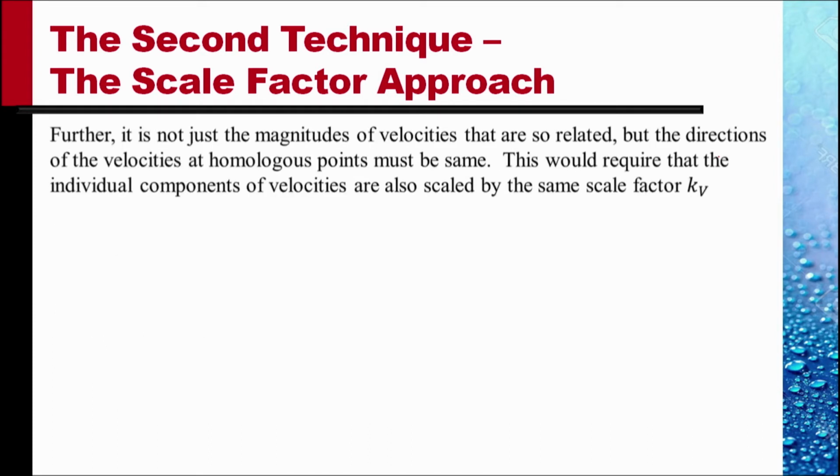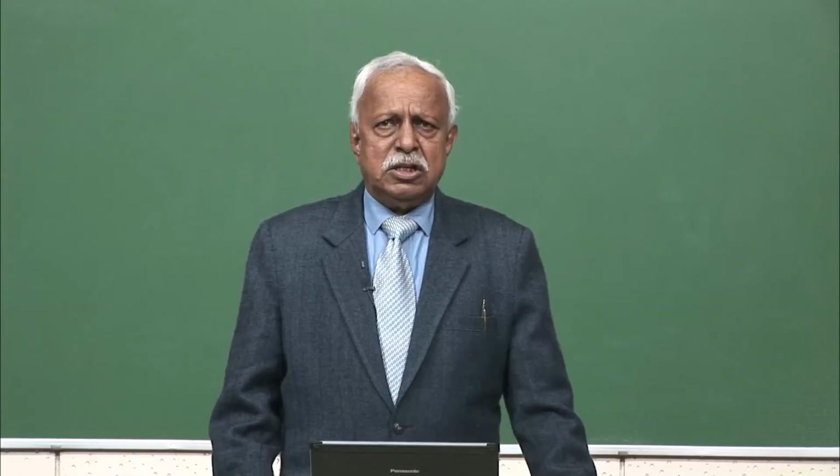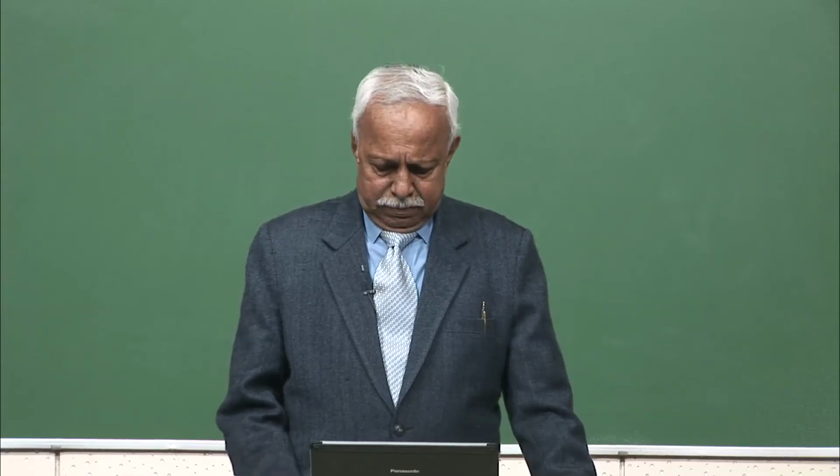Further, it is not just the magnitude of the velocities that are so related, but the direction of the velocities at the homologous point must be the same. This would require that the individual components of velocities are also scaled by the same scale factor Kv.